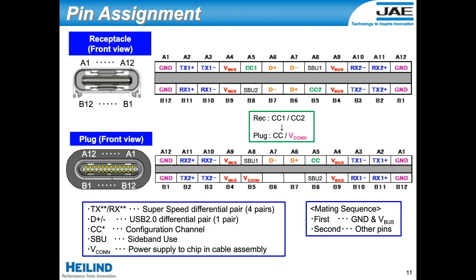And also there are going to be 2 SBU or sideband use pins. Those are unassigned pins in normal USB operation, but in alternate modes, those sideband pins can be used for different functions to support whatever the requirement is for that specific alternate mode.